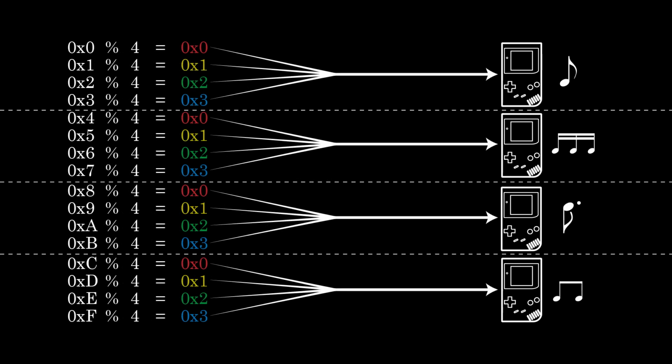In my previous video, we designed the multi-interface link system, which isolated the electrical signals of each Game Boy and translated all MIDI signals with an address value greater than 0x3 back into the range of 0x0 to 0x3. Our Raspberry Pi Pico took care of both this channel translation process and also made sure that the translated signals were only sent out via the GameLink cable, which was specifically reserved for the one Game Boy we wanted to hear play the corresponding note.